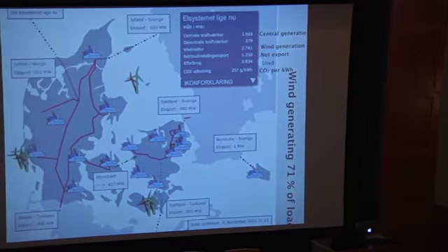So this is right now, Denmark, and we're running at 3.2 gigawatts of wind, and the load is 3.5. So what's that? They're running about 85% wind power right now. So this looks like that 20% maximum might not be correct. They're exporting. There's a fair amount of export here, 2 gigawatts. And they're still running some of the central plants. They're not turning it off completely for system stability and other reasons.